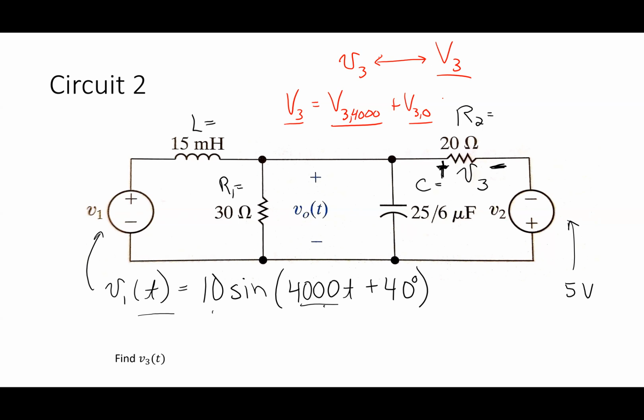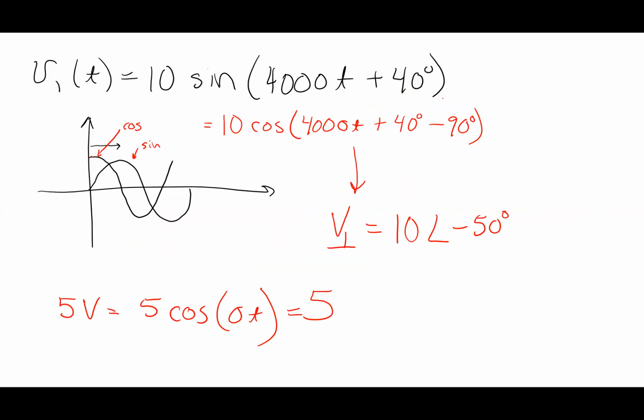Okay, so there's our circuit picture. I'm going to turn the DC off first. If I turn the DC off first, how does that simplify the circuit here? If I turn a voltage source off, what does it become? A short. So the 5-volt source basically goes to 0, and my circuit becomes V1, and then there's an inductor L. I think I called this guy R1.